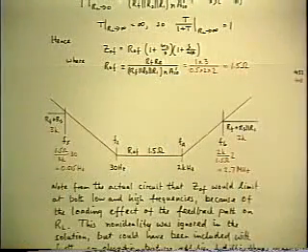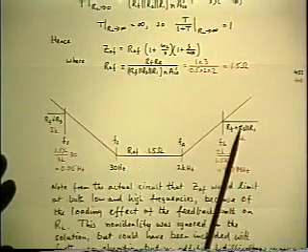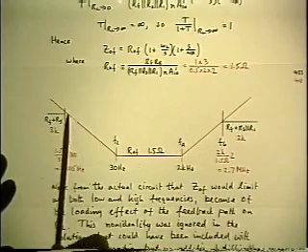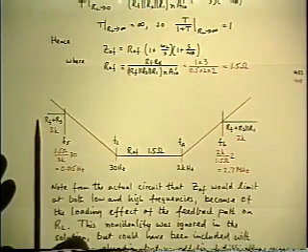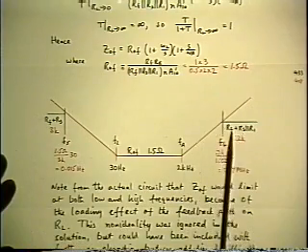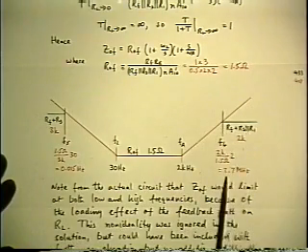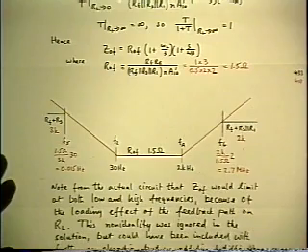And by gain bandwidth trade-off, you can determine where this corner frequency is, which is 15 millihertz. You could put those flat values in, and you get 15 millihertz for where this asymptote ought to level off at the value we expect. And at the other end, it ought to level off at a different value, and that would occur at 2.7 megahertz.